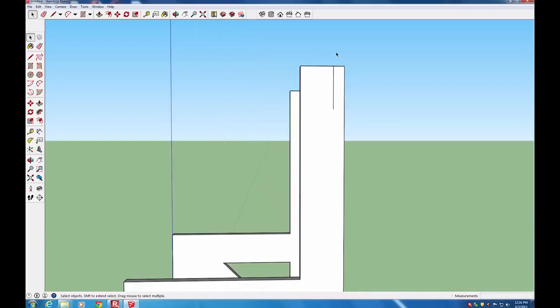So I'm going to zoom in up at the top where our first one's going to be. Select the rectangle tool from the large tool set. I'm going to start drawing from this corner of the line and draw it down. And we're going to type in 0.1, 0.05. That's going to make the correct size rectangle here.